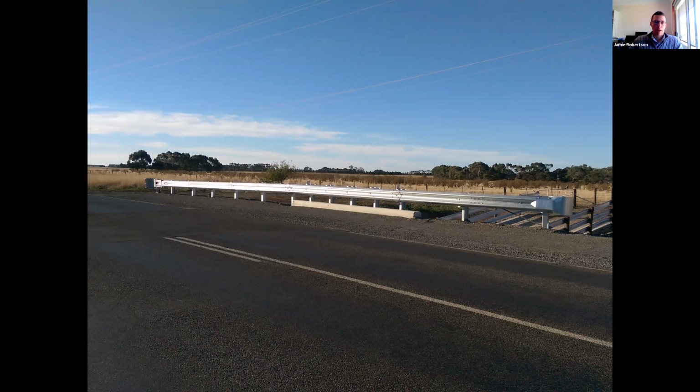We're not thinking that way anymore, so you would hope to see a grate on both ends. It hasn't been designed based on the run-out length method or angle of departure method. If it had been, you would see that the barrier would extend quite a distance further in each direction. And it certainly doesn't meet the minimum length requirements for a barrier.